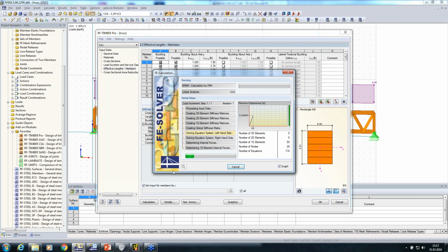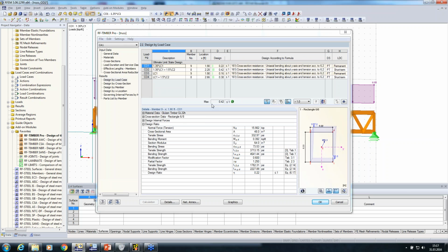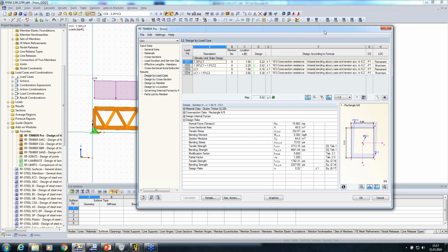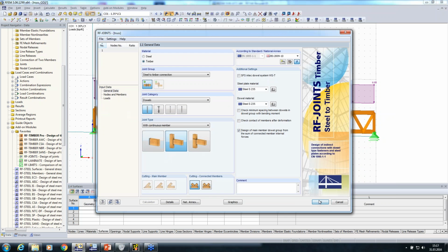Calculate the truss and will receive a loading. So it's pretty low loaded with 40%. That's pretty low, but we must also consider the connections in between, which will narrow the profile one more time. And so to have a loading of 60–70% is pretty common for this kind of trusses. And now I would go to joints, but I forgot one thing.